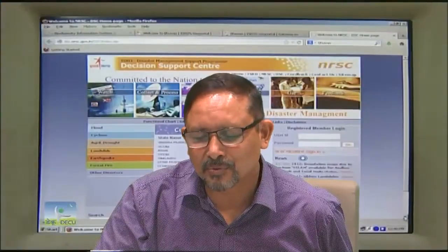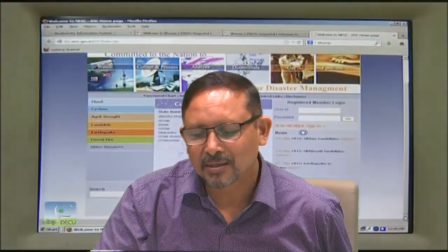So DEM is very important, even for drought, in flood and watershed, lowest elevations or valley areas. As I told you about the topographic wetness index, TWI, where you get a high value, that area will get more moisture and more runoff water. So there rainwater harvesting structures can be constructed, and you can mitigate the drought. Like that, you can utilize DEM.